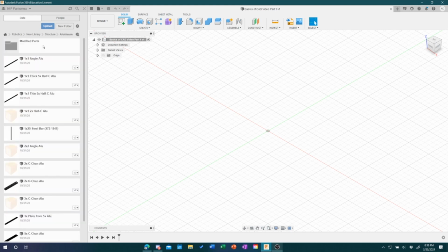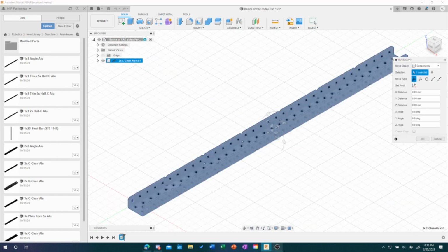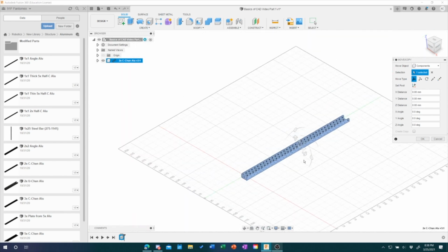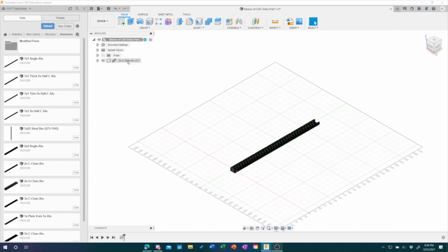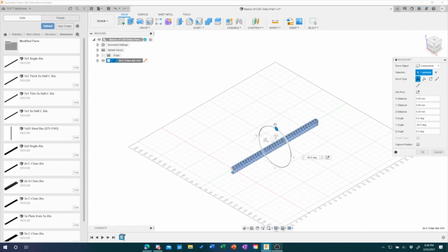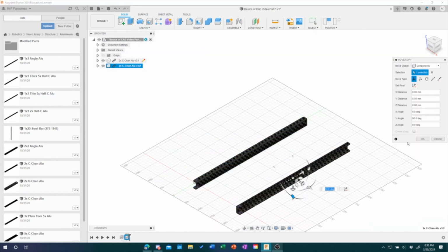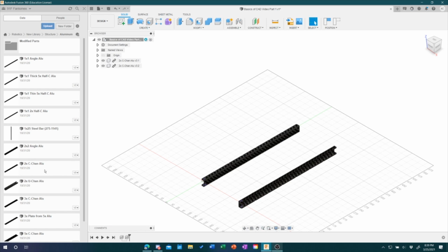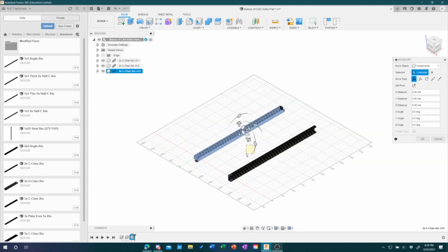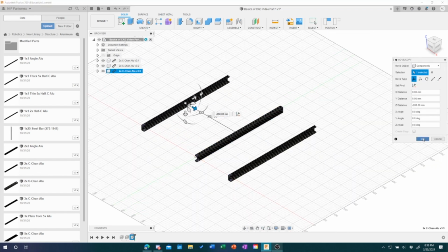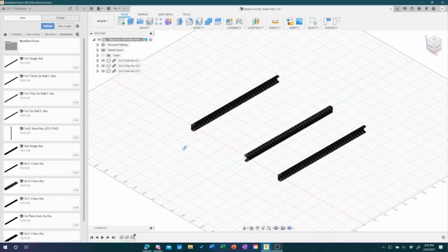Also, be sure to start off with the base as that is the foundation on which your robot will be built upon. Remember, each hole in a C-channel is a ½ inch. I start out with 4 35-hole C-channels, which is 17.5 inches to build the C-channels surrounding the wheels. As you can see, I rotate the C-channels in a way that the flat sides are on the inside. This is because in my final version of the robot, I want the flat sides to be in the middle so it is easier to build. I orientate the C-channels this way so it is easier to move on.